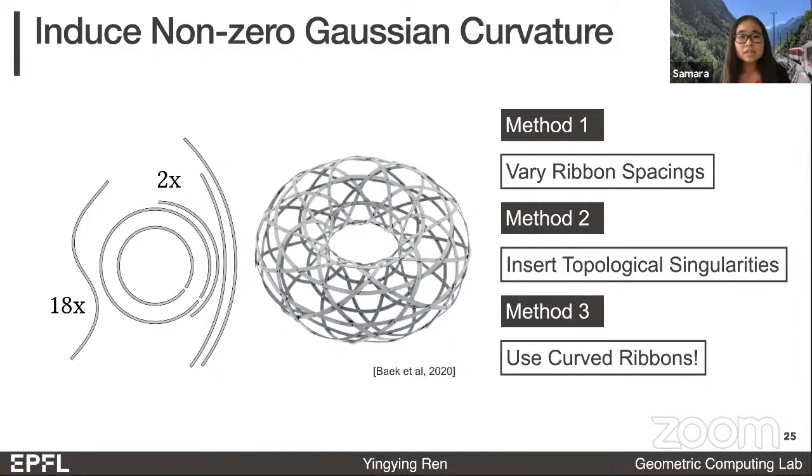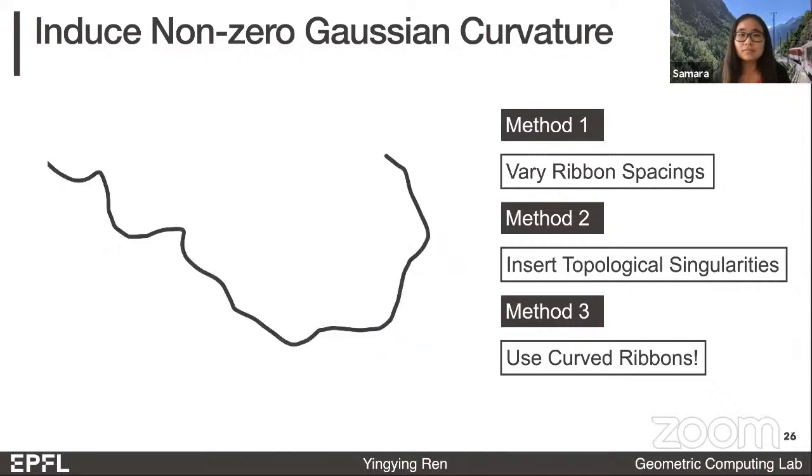Recently, a group of mechanical engineering researchers at EPFL, including two of my co-authors, applied this principle and created some simple woven shapes. They manually designed ribbons composed of straight lines and circular arcs, and showed that the shape approximation with these ribbons is better than using straight ribbons only. In this project, we want to optimize over ribbons of arbitrary curvature. This expansion in design space will increase the difficulty of the optimization problem, but it allows us to create previously impossible woven geometries.